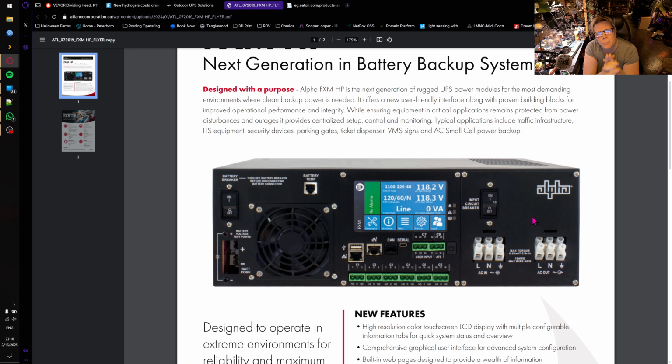One of you guys might be familiar with them and worked with them before, and if you have, please, in the comments below, link us to an article or explain in detail how that works, because I'm going to assume that when you're using a 48-volt module that there will be some sort of LVD mechanism or an additional sensor that you can pull in the OS to see what the battery status is, and you can set a low voltage disconnect point, an actual parameter in it that'll say, oh, well, we're running on 48 volts, that's great, but once you get down to 44 volts, yeah, it's time to shut ourselves down, okay?